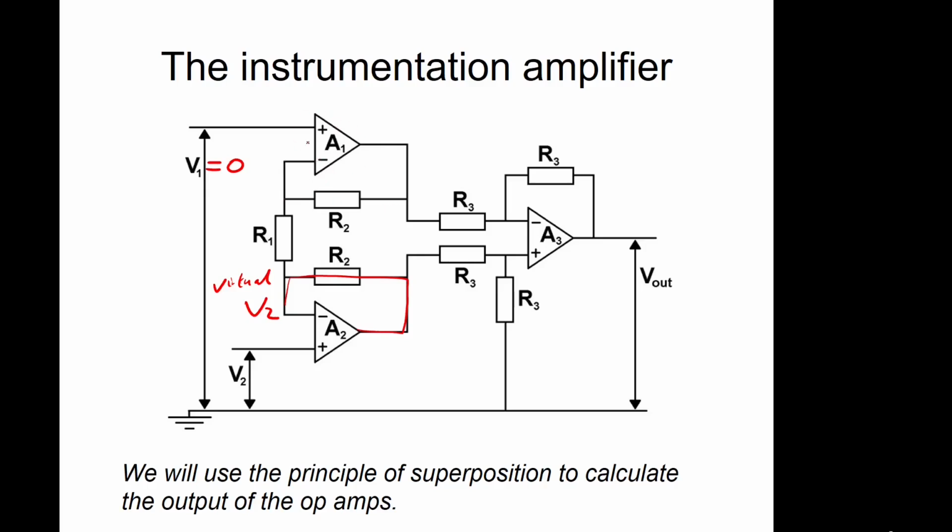So if you look at this carefully, and this point is 0, this is effectively earthed. So if you look at this arrangement carefully for A1, this is our inverting amplifier arrangement. It looks a different geometry because we've drawn it upside down, but if you look at how all the components are connected, it's actually identical to our inverting amplifier arrangement.